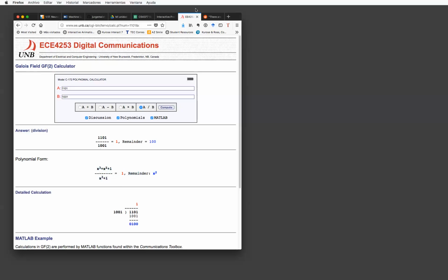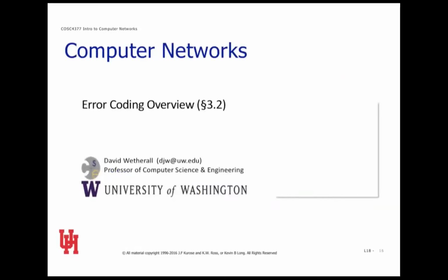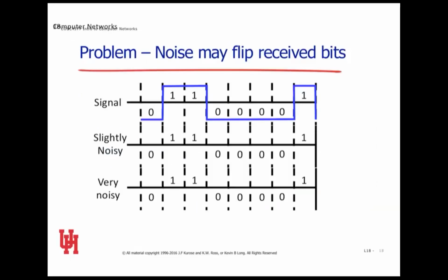Okay, off on the side. What I've left you in here is a little bit more data on how things work, and we're going to fly through and glance at a few of these things. And what I'm showing you here is from the University of Washington, and the credits are in there for the author. There's a signal that I'm trying to encode, and it's shown in blue. So I'll stick with blue, and we're going to show how you would encode the binary string 0110001. So here's 0, 1, whoops, I can't let go of my mouse, 0, 1, 1, then back down to the low part of the signal, 0, 0, 0, 1.